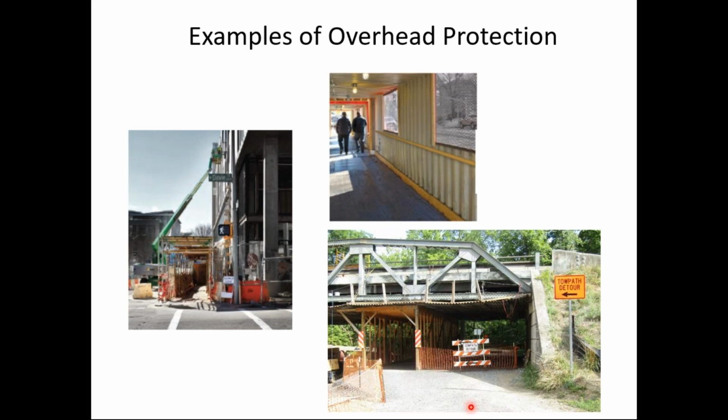The only thing I don't like about this is how they have the entry to the bridge. I should note the main trail is over here, but there's also a spur trail that connects to a local community that comes in here. So this is actually a trail intersection. And I think if it was my project, I would put in some edging or a barricade here that is detectable. You can see they have a sign, but remember that sign doesn't communicate with the visually impaired. And here's another application of the netting, plastic netting, but notice in my mind this is not appropriate because this netting is just hanging from a board or frame that's been placed across here. There is nothing at ground level, no edging that we talked about earlier. So this application of the netting, in my opinion, is not appropriate. It doesn't provide detectable guidance to the visually impaired.